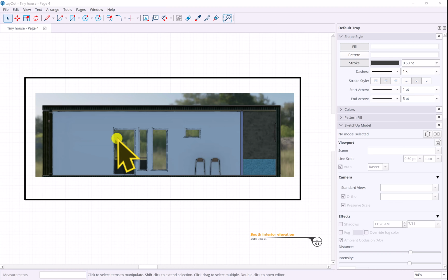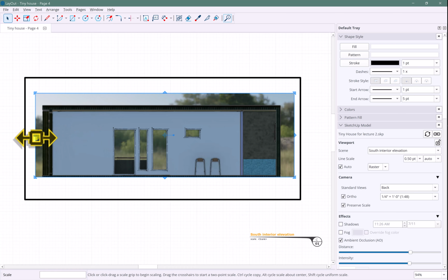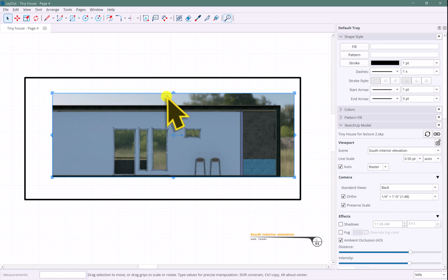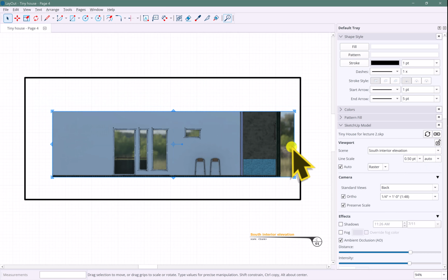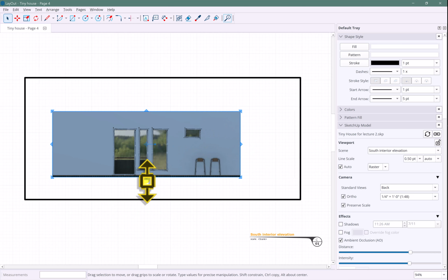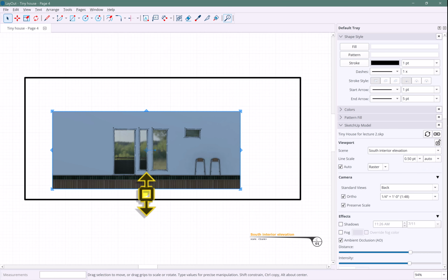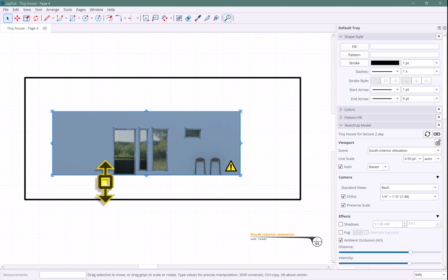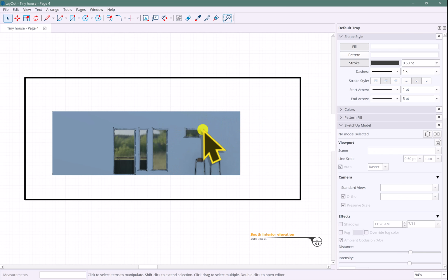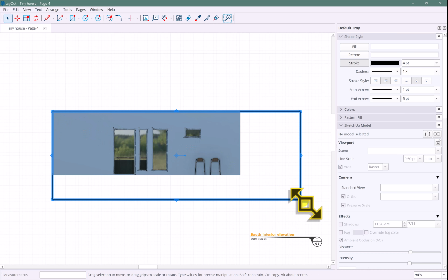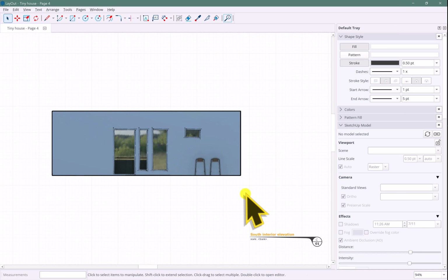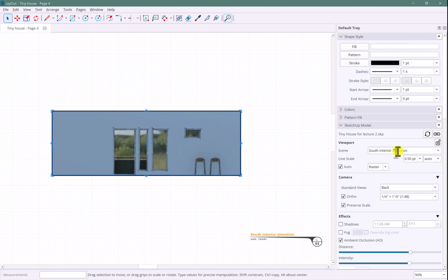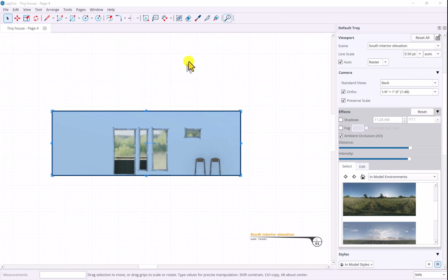Your elevations are particularly tricky because you should not see anything cut through. So make sure that you use your snapping tool here. And in this case, I really shouldn't see the bathroom. That would be a separate interior elevation. But to get the floor to crop away, I might have to crop up and then down in order to get the snapping that I want. Lastly, use that nice heavy boundary that we copied over from the other sheet, and there's your interior elevation. I may want to fiddle with the sun settings in order to get a nicer look, otherwise it'll be a little too dark.